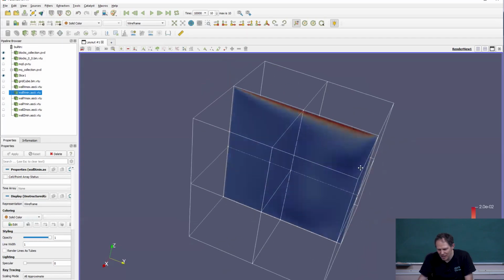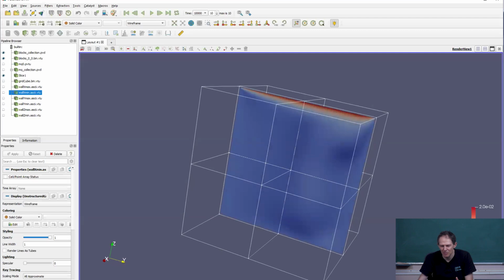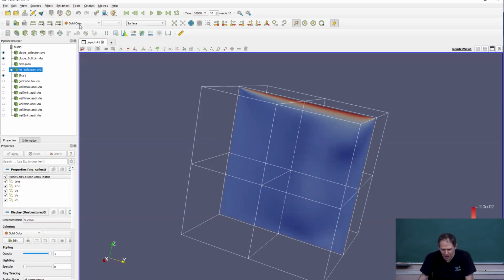Now I don't know whether you are familiar with ParaView. This is also used by OpenFOAM, for example, or you use it together with OpenFOAM. So you write out your data here, and what we usually write out is the density and the 3 components of velocity. The velocity is not written out as a vector.